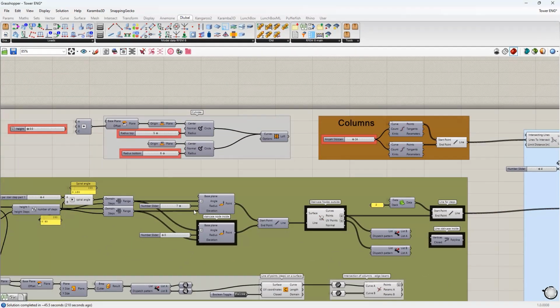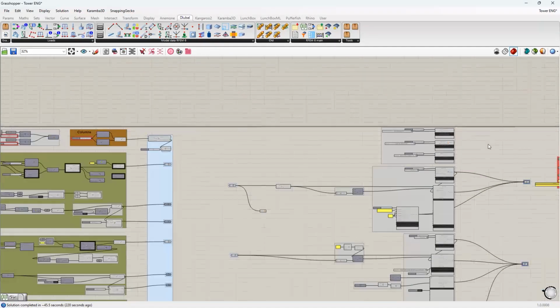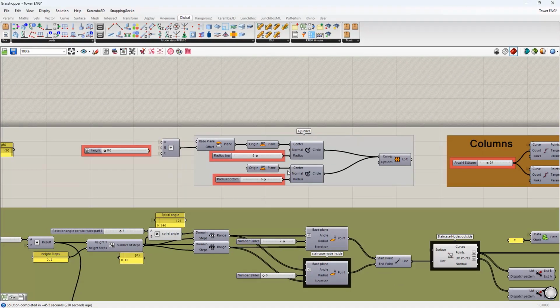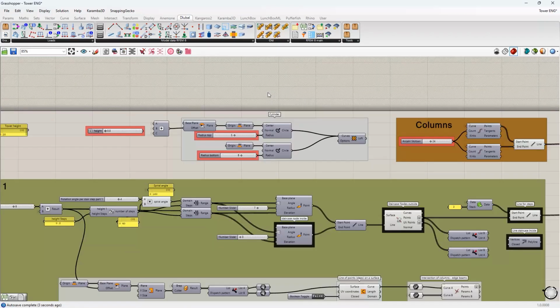And thinking one step ahead, maybe you can automate this design process. And now we have a large number of different configurations for the structure. We have our parameters, we have many possible solutions for a structure depending on the defined limits of these parameters and depending on the goal we aim at. But maybe at some point we have an optimal solution with the optimal parameter settings inside here, and for the future sure our aim is to optimize the process, to read out results into Grasshopper and optimize the structure based on these results we read out of RFEM.